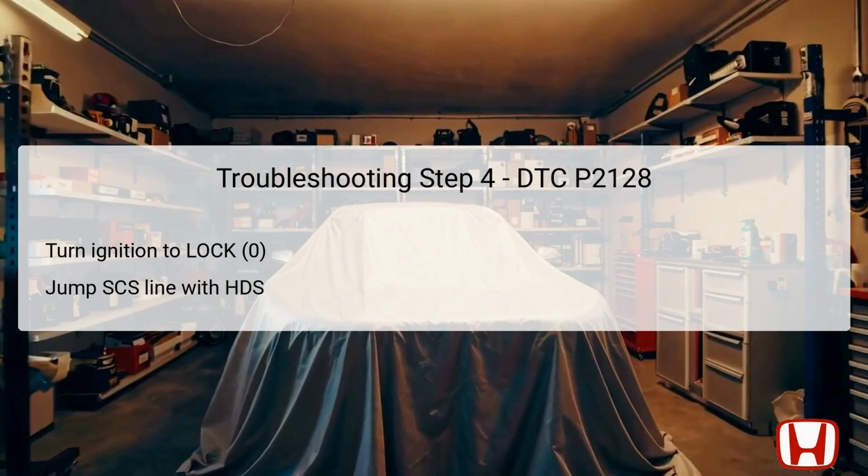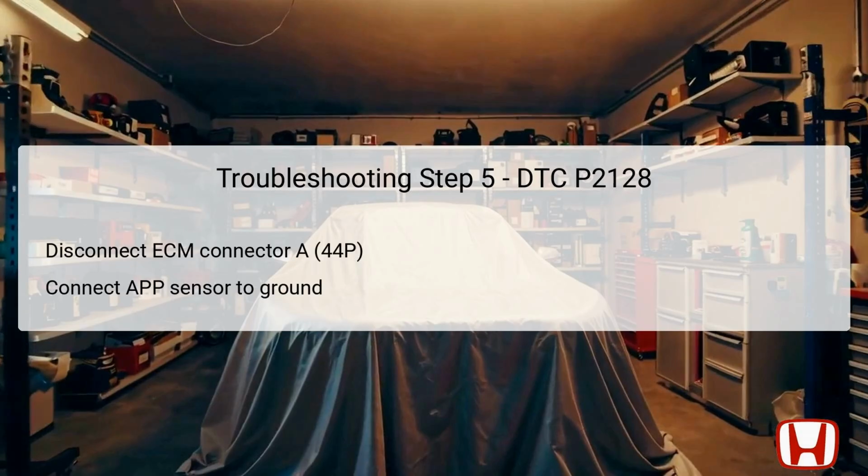In the fifth step of troubleshooting DTC P2128, the ignition switch again needs to be turned to the lock position to ensure safety. Following that, disconnect the ECM connector A, which has 44 pins, giving you access to the necessary terminals for continuity testing. It's important to handle this connector carefully, as improper disconnection could lead to damage.